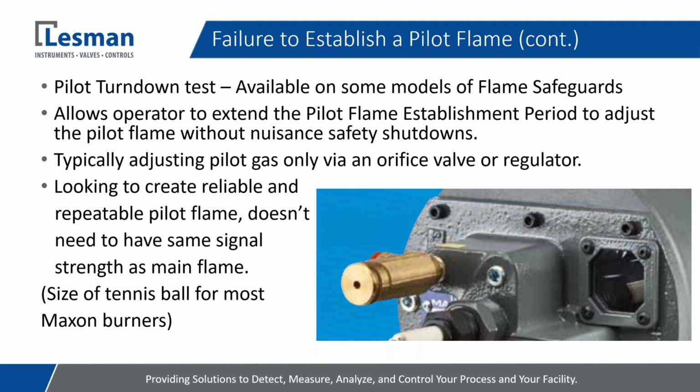But really, the main thing is that I have customers and people who are trying to get the maximum and peg out that flame signal strength, and that's a good thing. But I've also seen it where sometimes they go a little too rich, and then they get other issues down the road, like soot buildup on the igniter or the flame rod. So my advice is that it doesn't necessarily have to be the strongest flame signal. It just has to be repeatable. I want every single time that I go through a light off sequence to adjust that pilot such that it's lighting off each and every time, and the flame safeguard is picking it up and recognizing it.